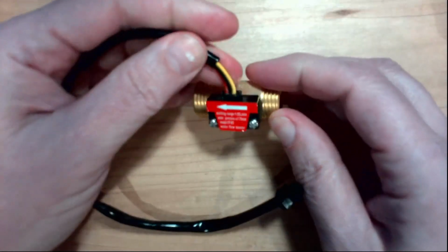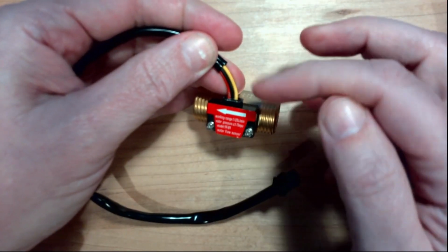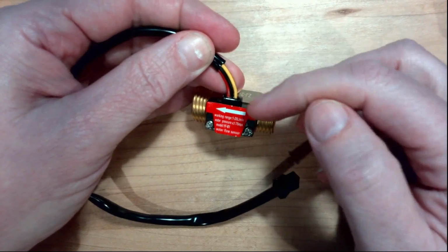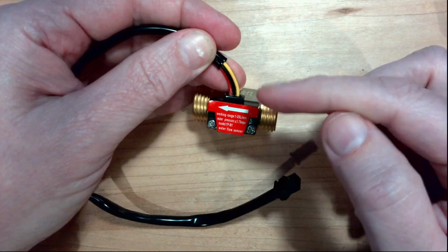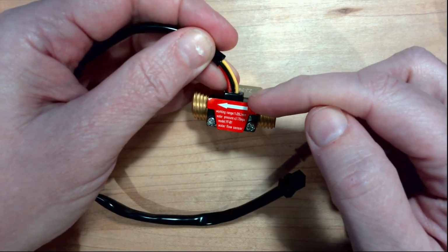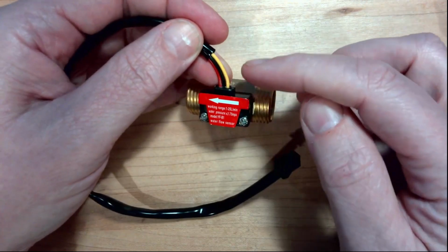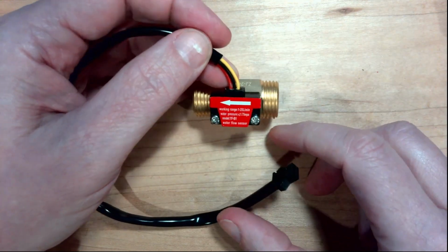So when we have one of these, they pretty much all have 3 wires: power, ground, and signal. So what we do is we hook it up and we give it power, usually in the 5-volt range, though they usually have a pretty wide variety of ranges that they can accept. And then we listen for pulses on this signal line. The pulses that come in on that signal line can come in kind of quickly.